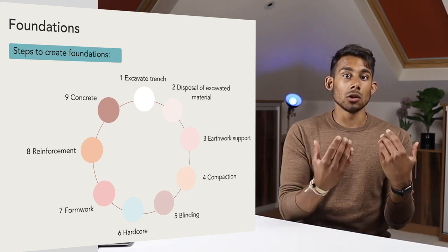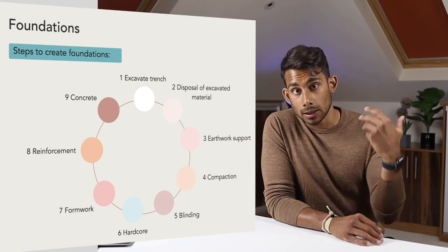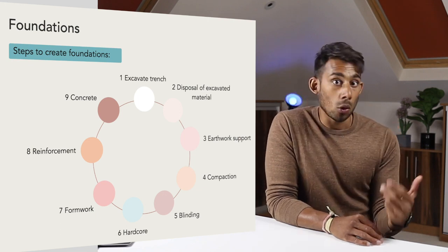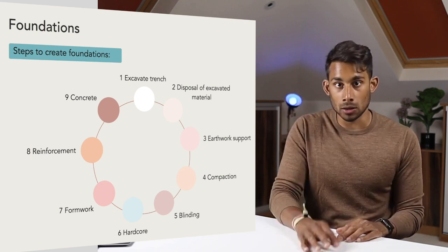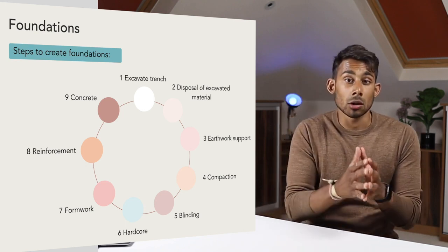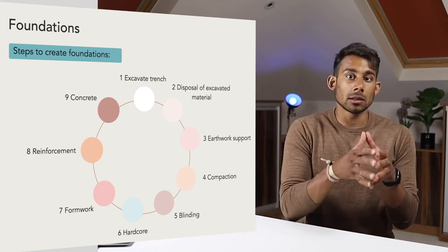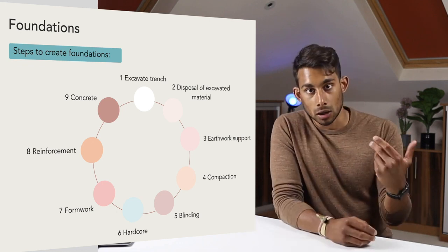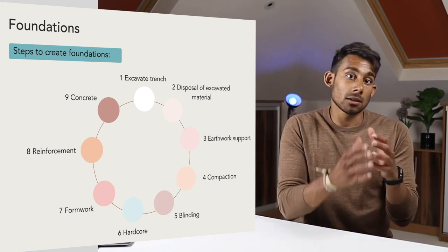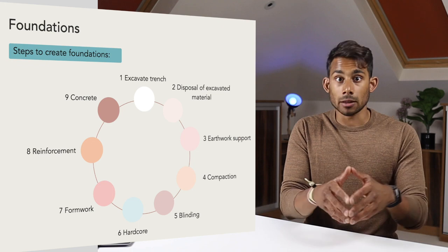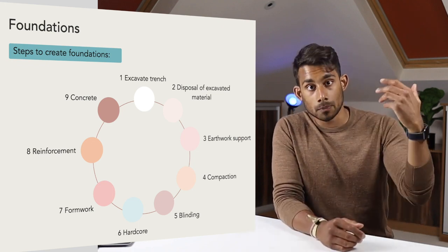Next, you would need to use a concrete pump. Using a concrete pump is perfect when you are dealing with large volumes of concrete or when time is tight and you don't have the manpower to use wheelbarrows, for example. You can pump approximately 1 meter cube of concrete per minute. You will also need to use a pump if the concrete mixer truck can't get close enough to the pour area or access to your site is restricted, underground, within an existing building or at a height.